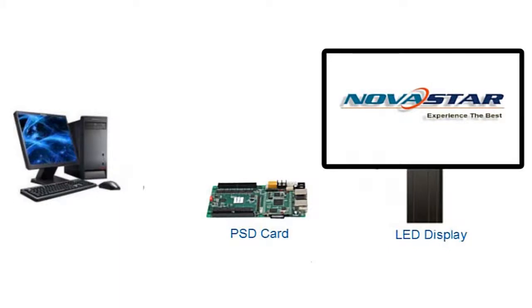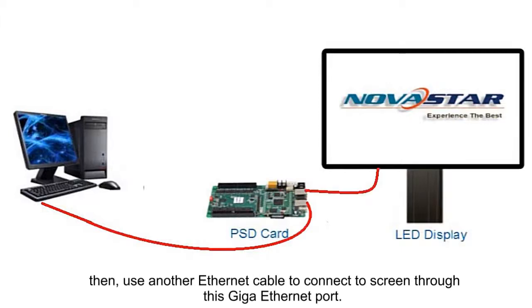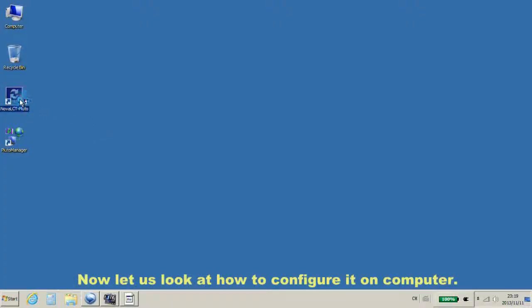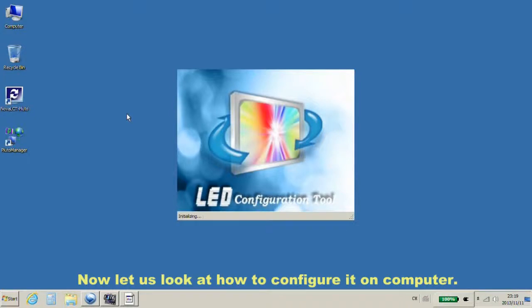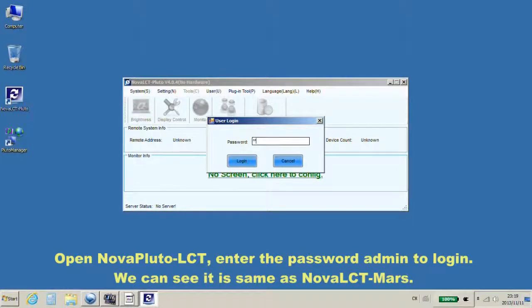Now we are going to configure a new LED screen with a PSD100. Firstly, use an Ethernet cable to connect to the computer through this mini Ethernet port. Then, use another Ethernet cable to connect to the screen through this Giga Ethernet port. That is about hardware connection. Now let's look at how to configure it on the computer. Open Nova Pluto LCT. Enter the password admin to log in.